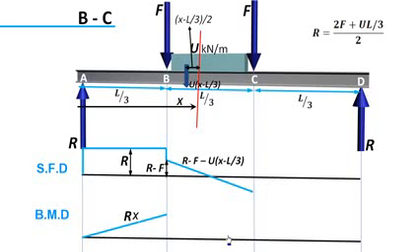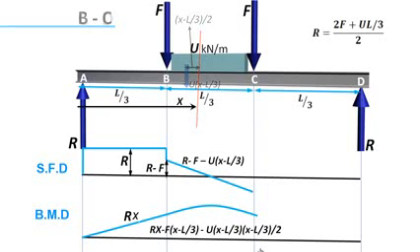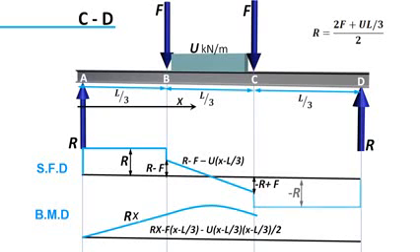You can easily predict how bending moment varies along length from the same force diagrams. Since this equation is quadratic, it will have a parabolic shape. Same procedure is repeated in the remaining sections. Since this problem is symmetrical, bending moment and shear force have a symmetrical distribution.